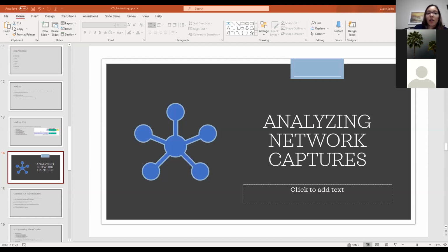You could very easily take one of these packets, modify the data, and send it back to the PLC, and then you could be doing a replay attack, or a man in the middle. Thankfully Wireshark is really nice, and it has this Modbus TCP interpreter, so you don't have to look at the bits by itself.